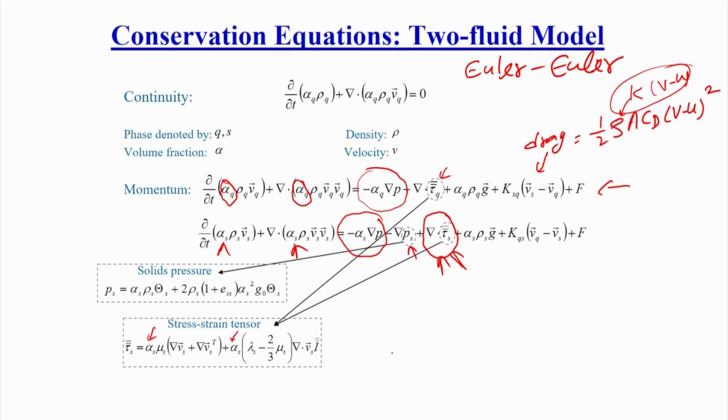If you just open the transport phenomena book, you will see that the tau has been defined in this way. There is a reason to define it this way, because the tau is a symmetric tensor. That is why the other transpose term has been used, so that you get the symmetric nature. The volume change can affect the viscosity, that is why this term has been used, and if the fluid is incompressible, this del dot V term will be 0 with the continuity equation.